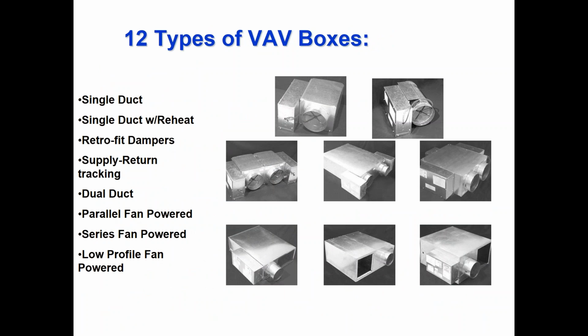Types of VAV boxes. I wasn't going to go into these in really long detail. I am going to save that for another day, and I'm just going to talk about these generically for you right now. And we'll save VAV boxes for a separate topic in July for those that are interested. But the ones that you're going to see most often are going to be single duct VAV boxes, which just means it's just a damper.